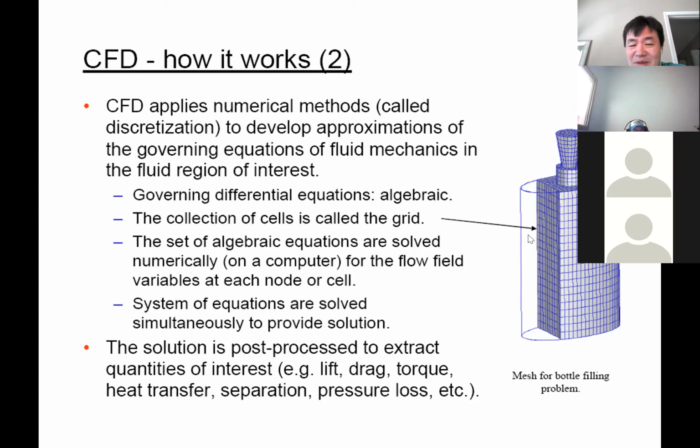If you try to simulate the flow over the house, a hurricane wind blowing over the house, your volume of interest is the volume around the house, outside the house. So you place your mesh in the volume outside the house, not inside the house. You don't care about the flow inside the house. If you have a flow inside the house, your house is gone. So you're interested in the flow outside the house, right?